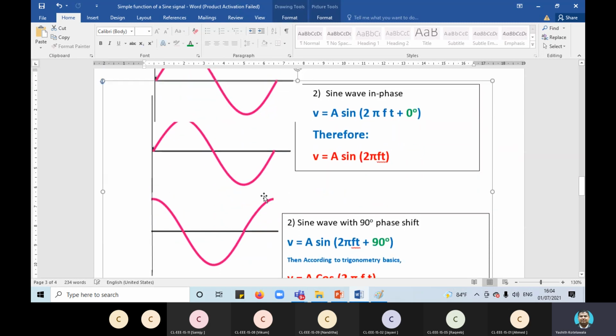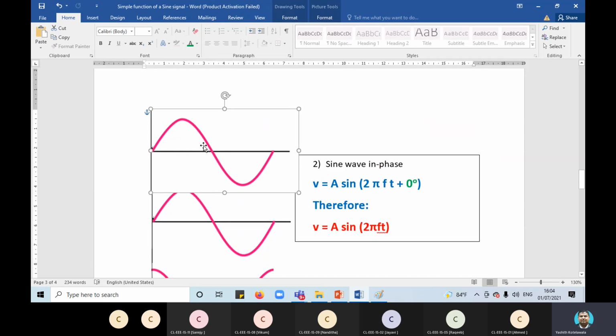Now this is superpositioning. Here this is 0 volts, this is 10 volts. So this entire alternating signal is going to stay on top of 10 volts. The original wave input signal is superposition on a direct current component. This is what basically happens in a transistor outcome.